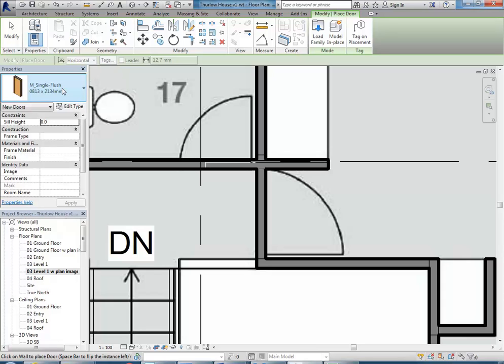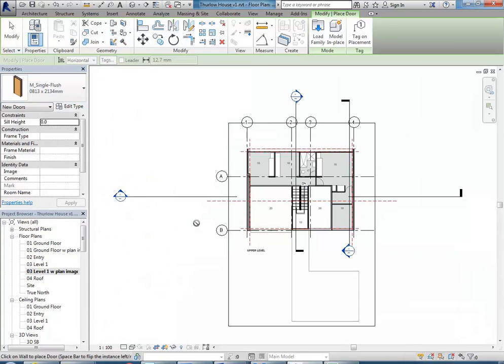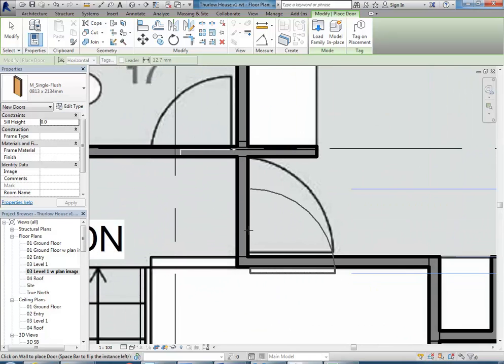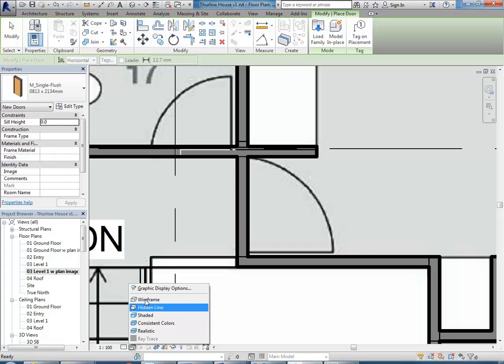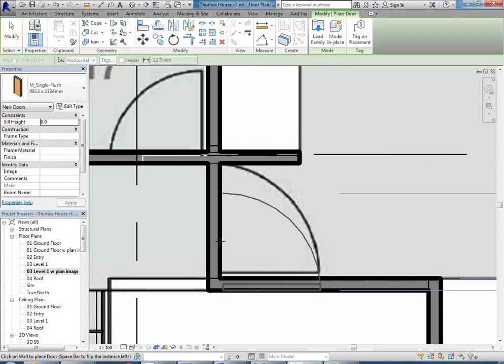They don't show things like door jambs in their floor plans, generally, which is a bit off-putting, really, because it's a good thing to be able to see them. Now, before I even place this door, I want to see the door jamb in plan, so again, I know what I'm working with. And remember, we've set the view to wireframe already, but now that I've got some walls there, the grey is hiding the door, essentially, where I want to see it.